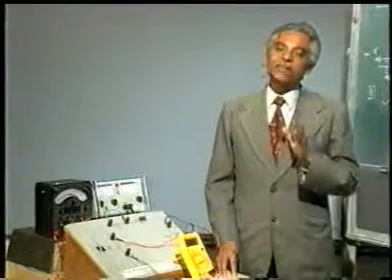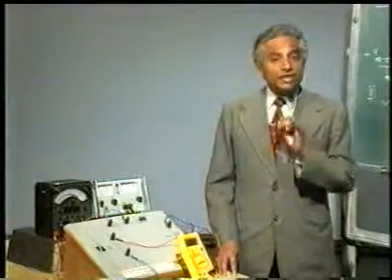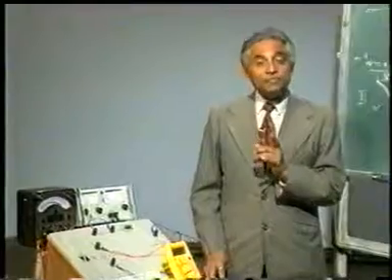The diac is a bidirectional device and we know its VBO also, and correspondingly we have seen the voltage drop when the diac started conducting. The voltage drop was very less across the diac and the current shoot was very high. The maximum current we got in this case was 0.3 amperes. So like that we have verified the VI characteristic of a diac.